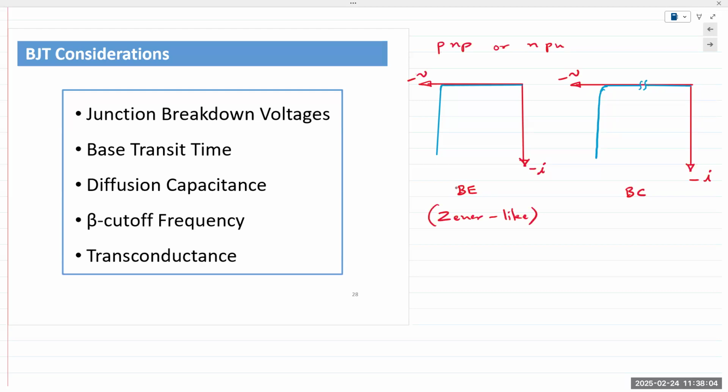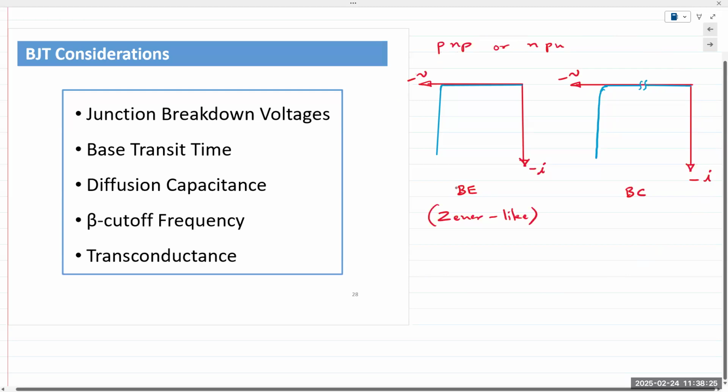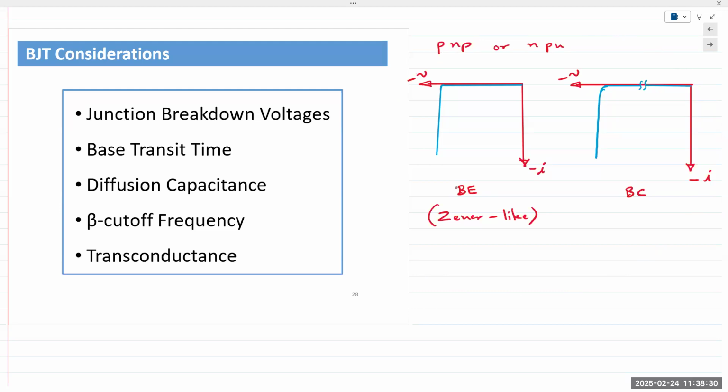So in the lab, at least in my lab section, what I like to do is at the beginning of the lab, you would take the transistor. No need to, I mean, say no need to look at the spec sheet. That's the wrong advice to give to students. But before you look at the spec sheet, we can use this to determine the pinout of your transistor. Okay, so in the lab, the base for a transistor would be in the middle. You have 3 pins. The middle pin would be the base. The other 2 pins would either be the collector or the emitter. We don't know which one is which.